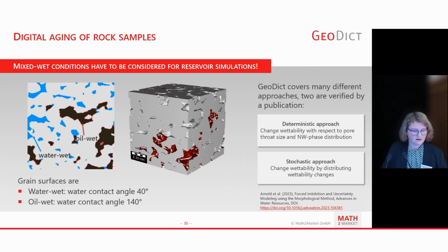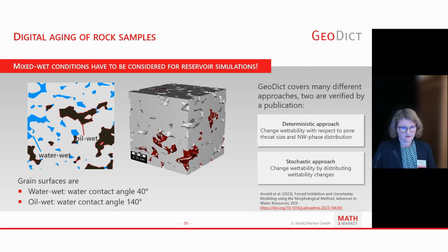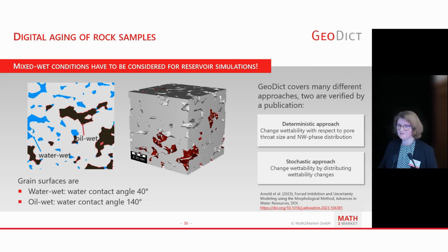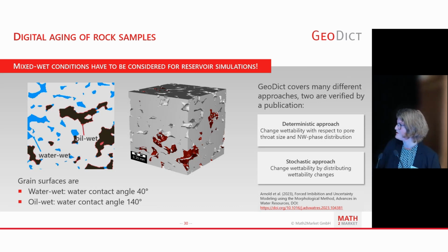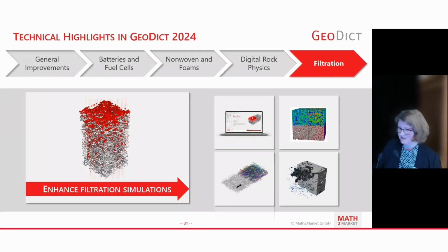And then there's another new topic for digital rock physics, which is mixed wet conditions. They have to be considered for the reservoir simulations because mixed wet conditions are created when the oil is pushed out of the reservoir during water flooding. And some pores can only be flooded with water at a really high external pressure due to the oil that is still on the surface. And thanks to GeoDict's mixed wet surfaces, this flooding process can now be simulated, and also the corresponding relative permeability can be calculated. And we have many different approaches to do that in GeoDict, and two of them, the deterministic approach and the stochastic approach, are verified by this publication you can see here on the bottom.